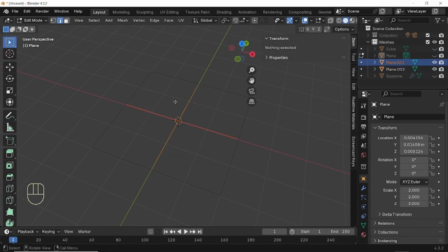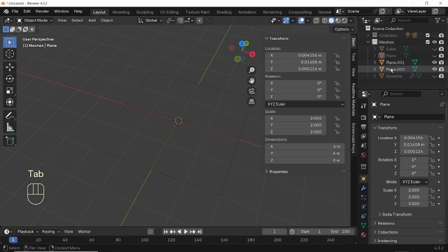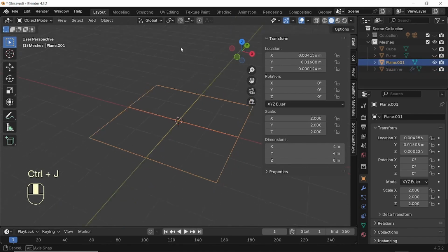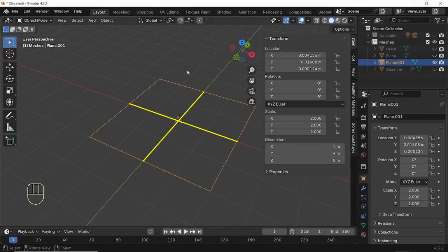Return to Object mode. Now let's join the edges into a single object. Select the separated objects and hit Ctrl J to make a single object. The last operation merged the two objects into one, but kept the meshes separated. Now we can merge the meshes into one.